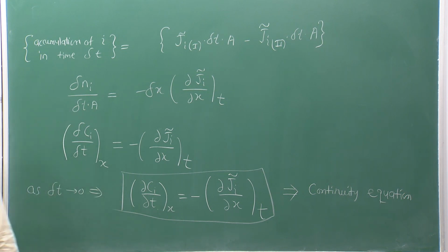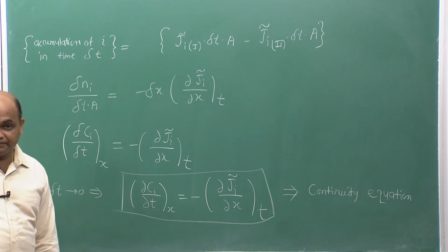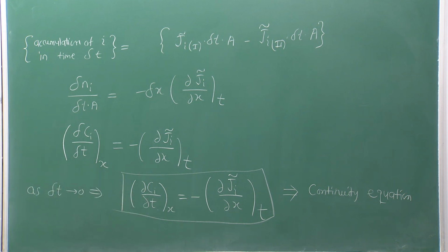Typically, in the diffusion in solids that we consider, especially when the diffusion is defect mediated, like for example, vacancies, there may be production of excess vacancies or loss of vacancies to the sink, and that might affect this term Ci here, because it affects the site fraction of species i.